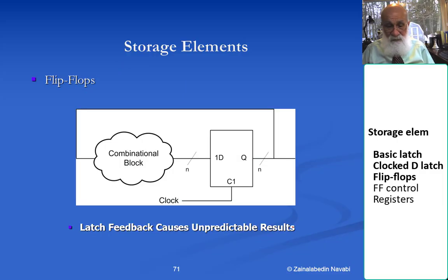And actually, this is what I talked about already with the flip-flops. This situation doesn't cause a problem. If I have latches here with the feedback, this is going to create unpredictable results because I really don't know how long the clock is on and how much propagation is going to happen because of the delays. With the flip-flop, I'm pretty sure that the combinational logic will only pass through one clock and then the feedback will not happen until the next clock.